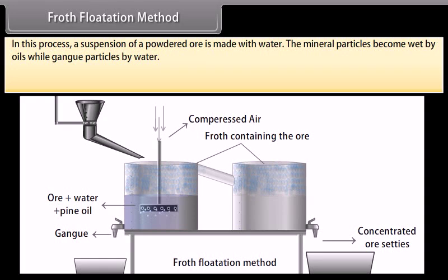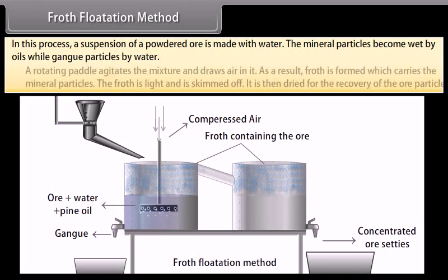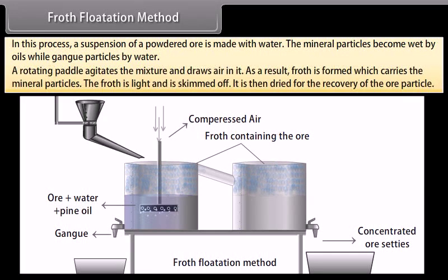Collectors like pine oil, fatty acids, and xanthates are added to it. Froth stabilizers like cresols and aniline stabilize the froth. The mineral particles become wet by oils while gangue particles by water. A rotating paddle agitates the mixture and draws air in it.